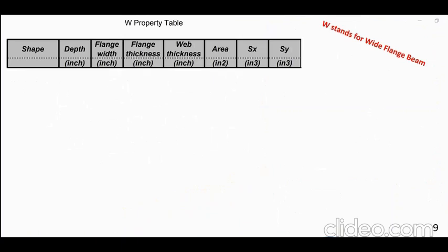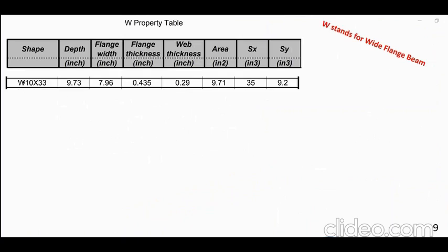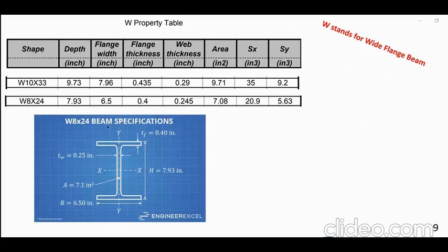Now, very often mechanical engineers don't do this, but it's kind of unfortunate. First of all, the W in that designation W10x33, W stands for wide flange, okay? And there are tables like this. I'm sure you saw it in your Hibbeler's book too, when you took stress analysis perhaps, or your deformable bodies class. In the back there are tables of the different types of wide flange beams. These are the designations for the two beams that are being used here. Let's concentrate on this one.